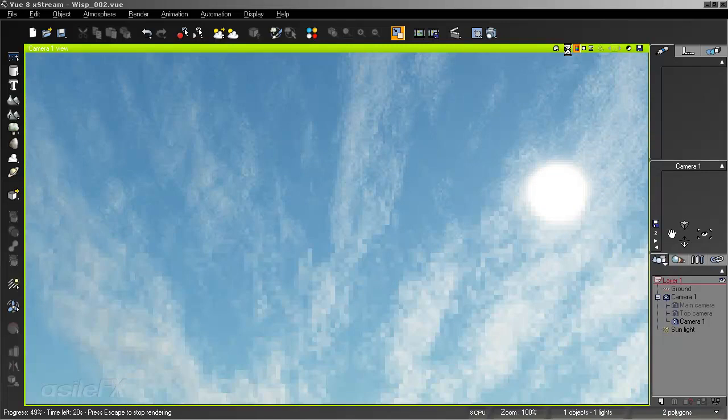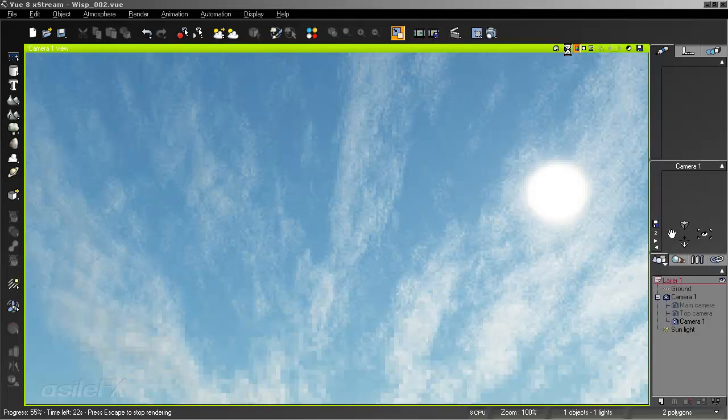Depending on the scale of the function, the fractal, you would want to avoid any roughness settings larger than 0.5, because it's going to cause a lot of grain and a lot of little in-between values, and that could cause grain within the lighting and the anti-aliasing.